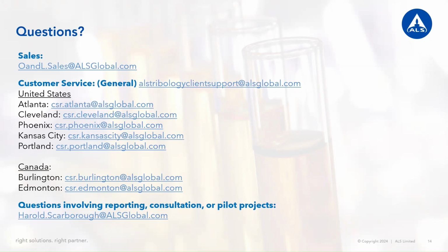If the information is provided from your samples, say if you're sending in samples and you provide the time on oil, whether that be hours or miles, we can correlate this to TBN value. And this gives us an accurate way to graph this out and provide a rough estimate of where the eventual oil end of life is.